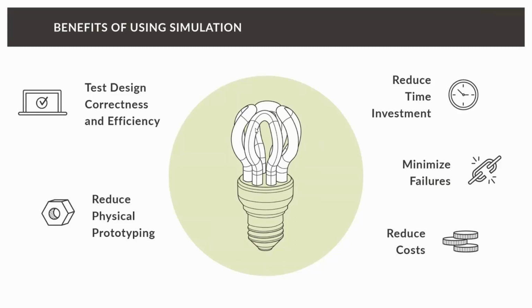If I do, for example, a physical test, a wind tunnel test, I need to measure all the quantities I'm interested in during the run. So if I want to know about the forces, I need to install a wind tunnel scale. If I want to measure the pressure at points, I need to install pressure probes. And whatever I don't measure during the run is lost.